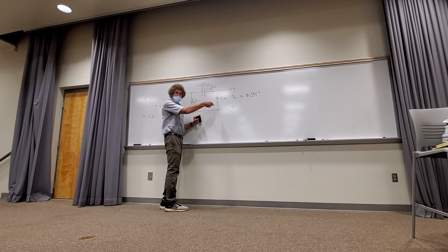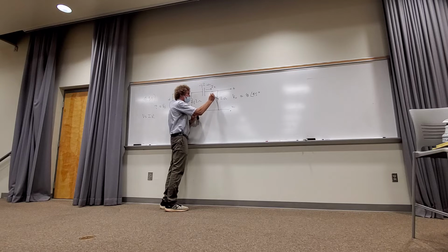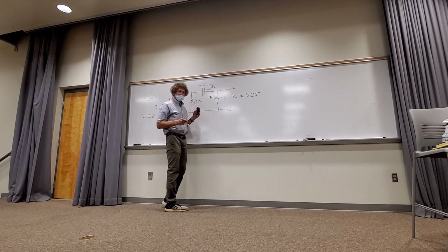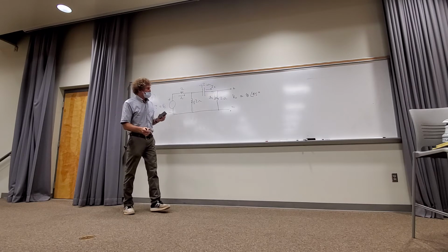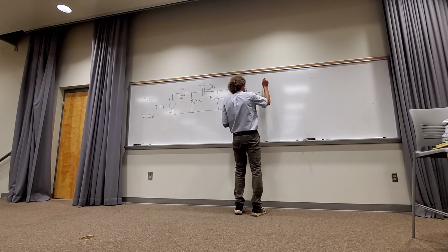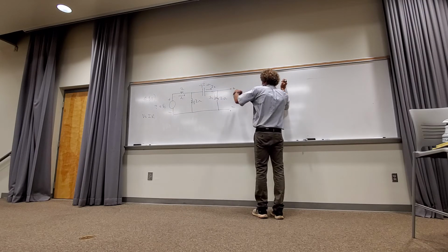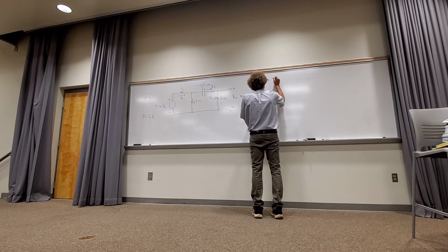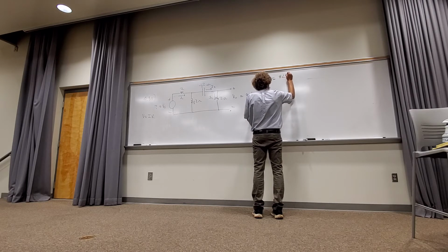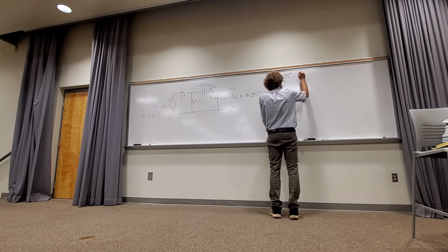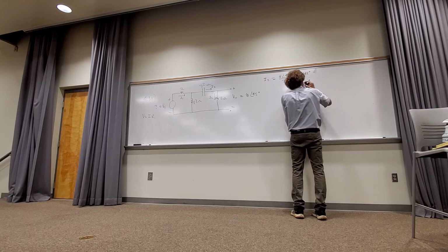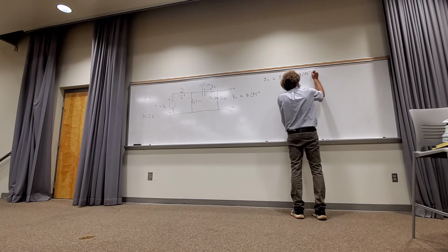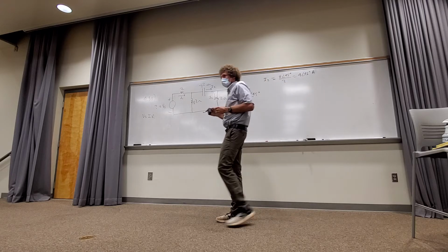Are they not, class? Therefore, if I know the current through here, this has to be the current through that capacitor. Do you agree with me, everyone? Let me see your hands if you do. So what is that current? What is I2, class? Well, the voltage is here, right? So it would be 8 at an angle of 45 degrees divided by 2, or 4 at an angle of 45 degrees amps, right? Okay, I got I2.